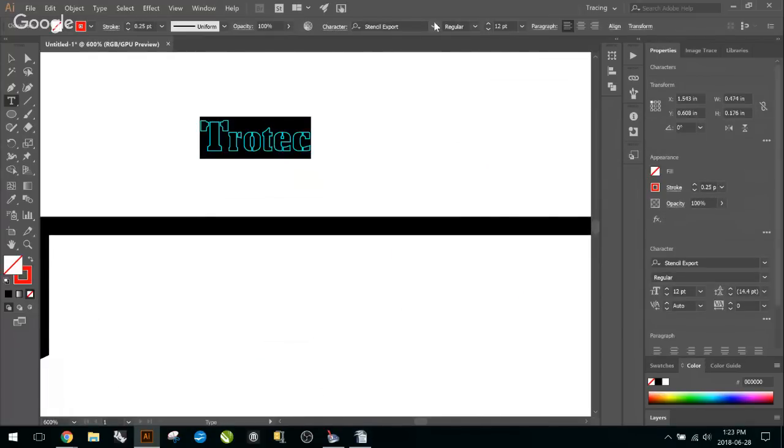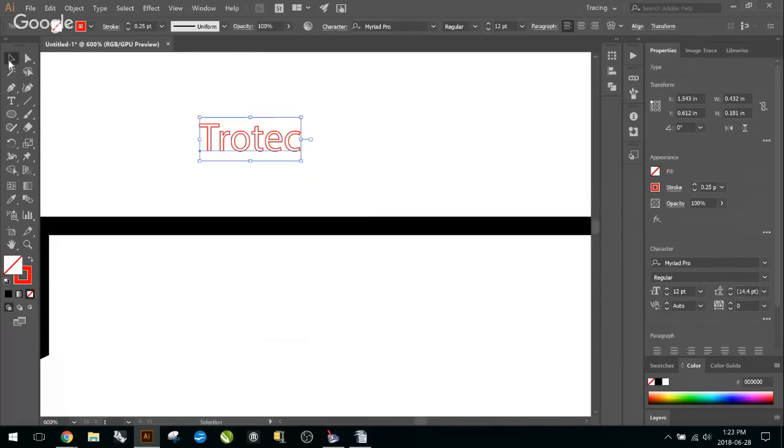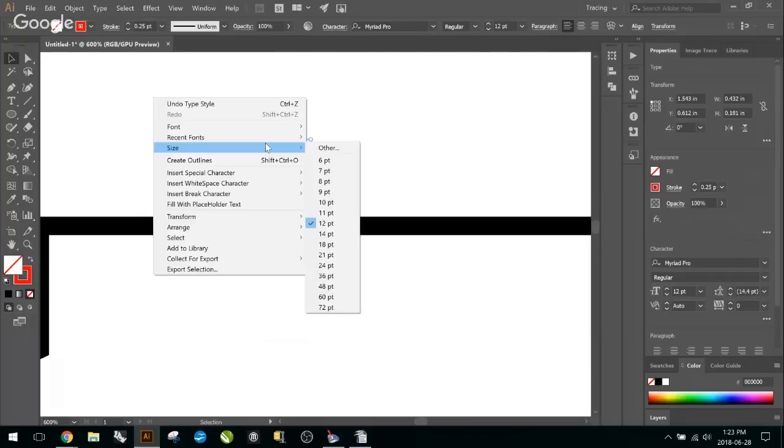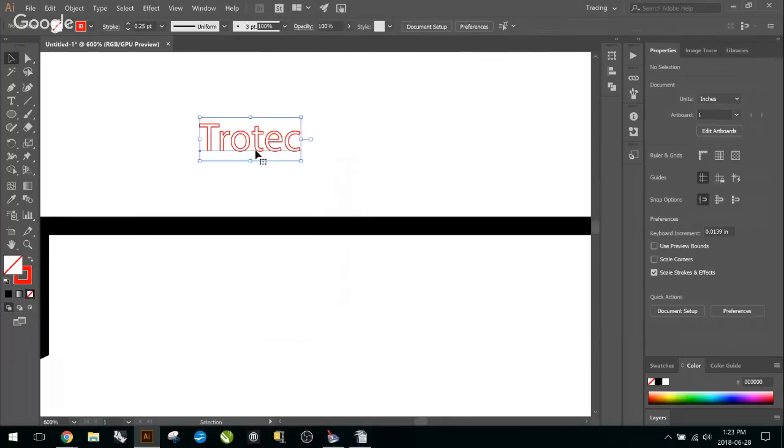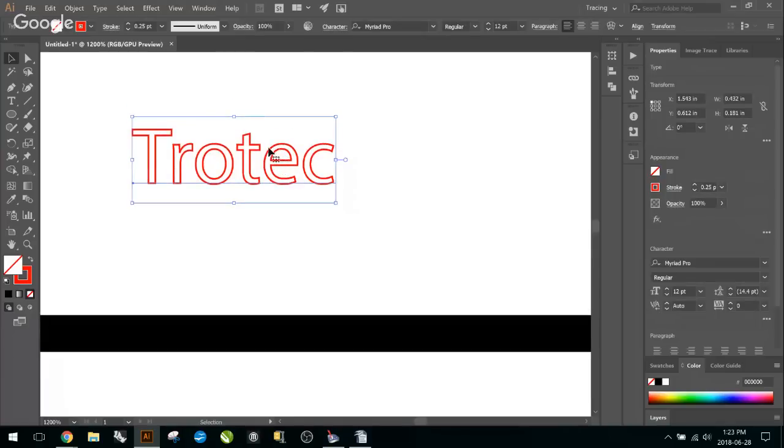I think the answer is to convert that text to a shape and break the curve apart, and then delete the inner cut. So let's say it's a Trotec engraving text and you're trying to cut out just the shape of the text around without the inner cut, like on the E, for example. Do you know what I'm saying?